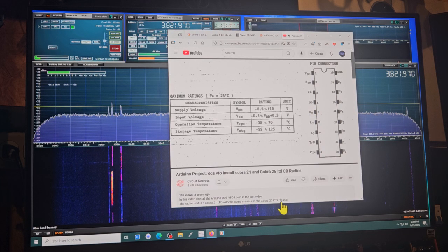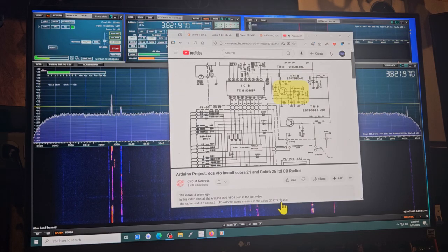or VCO. The PLL also takes a signal from the reference oscillator. In a typical AM/CB radio, the reference oscillator runs at 10.240 MHz. The PLL uses this as a reference to measure feedback from the VCO to perform calculations to ensure it is on the correct frequency. The reference oscillator is also mixed with the VCO signal by the radio in the transmit and receive mixing circuits. This is the reference oscillator in the schematic.